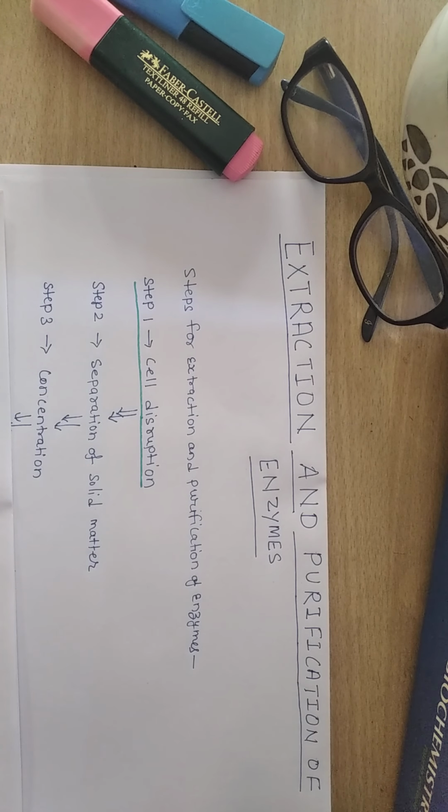The desalting of enzyme solutions can be carried out conveniently by diafiltration. The small salt molecules are driven through a membrane with the water molecules and the permeate is continuously replaced by fresh water.